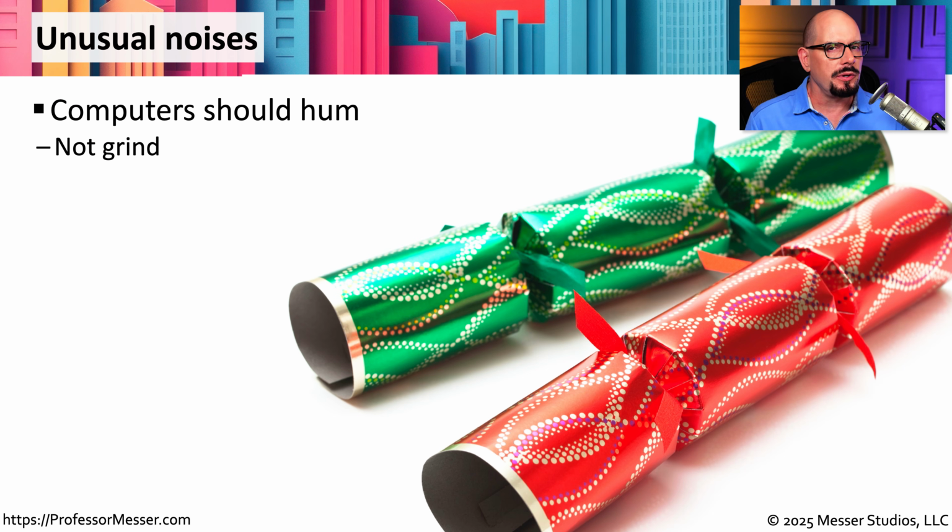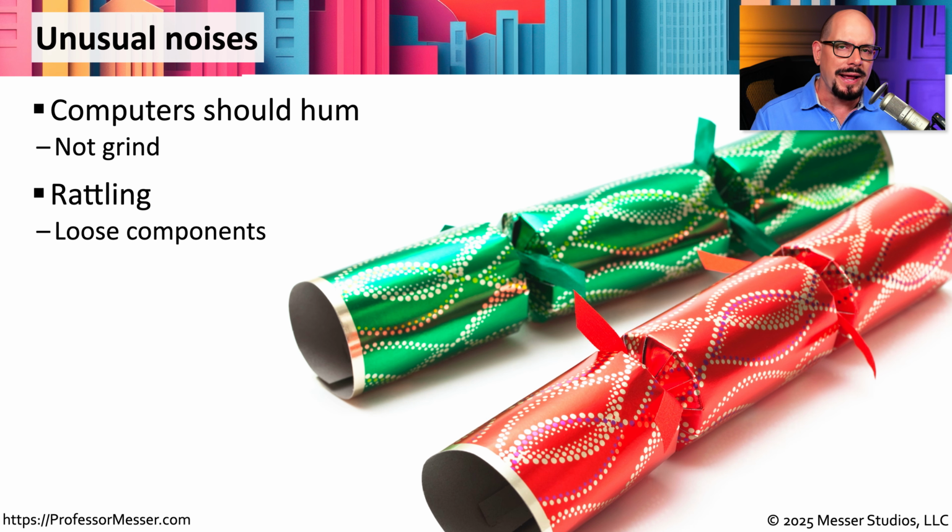If you turn on your computer and you hear some grinding noises, then you know something is probably going wrong. Most computers are either very quiet or have a small hum associated with them, so hearing any type of unusual noise should automatically make you think that something's not performing as it should. If you hear rattling noises when you're moving the case, then something has probably come loose inside of the computer itself. Very often this is a heatsink, and you can simply reinstall the heatsink with some thermal paste.